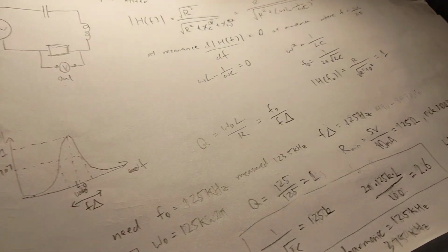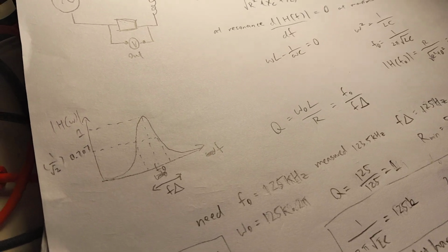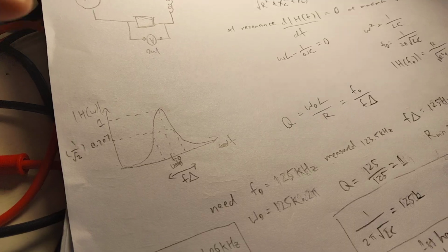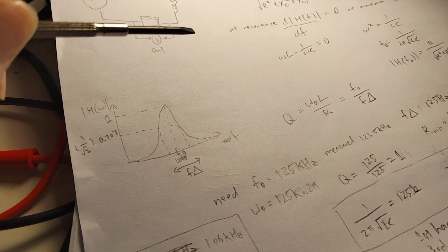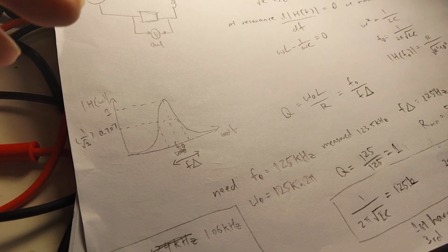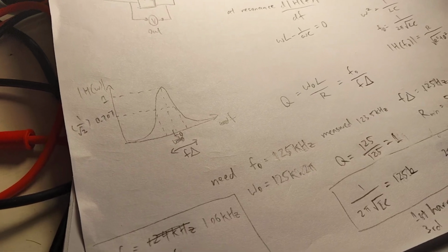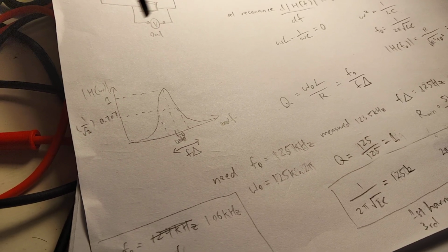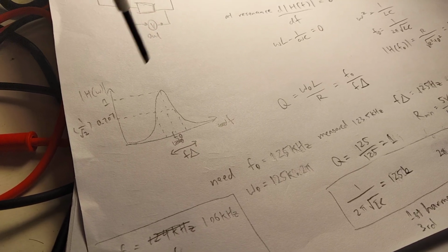Because what happens with a PWM wave is because of the Fourier series transform. Any wave is comprised of a number of sine waves at different frequencies and at different offsets. What happens with a square wave is that because it's a regular interval, the sine waves which make up that square wave are going to be the odd harmonics plus the fundamental frequency.